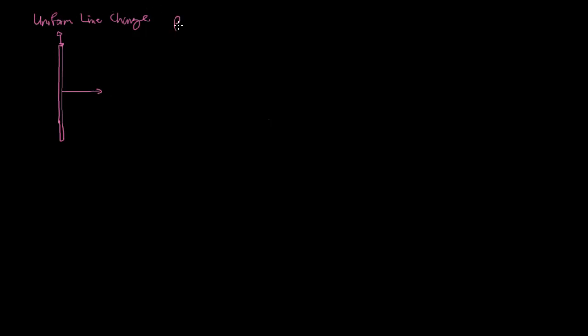So we have a uniform line charge, rho L, along the z-axis. It runs along minus infinity to infinity of the z-axis, and you want to find the electric field. So this is the z-axis. It runs all the way along, so we'll just draw this out, extends this way. And as we described before, we see that this is cylindrical radially along the z-axis. So that kind of implies that we might want to use the cylindrical coordinate system.